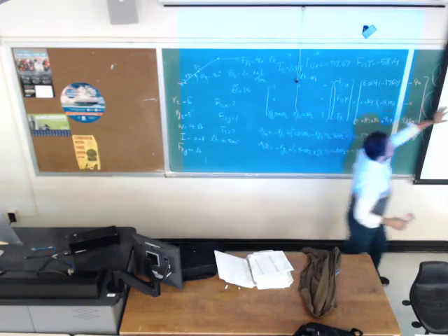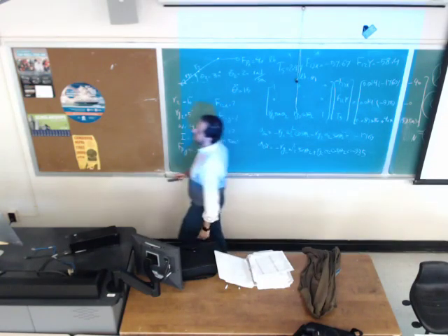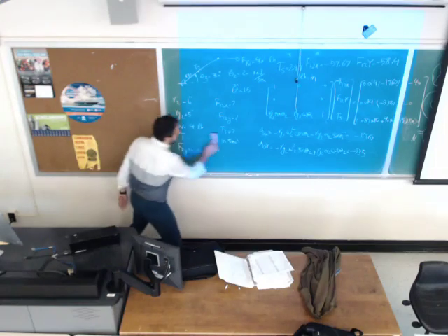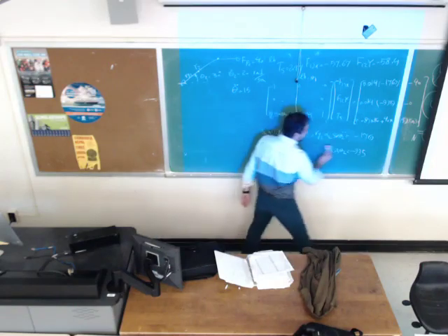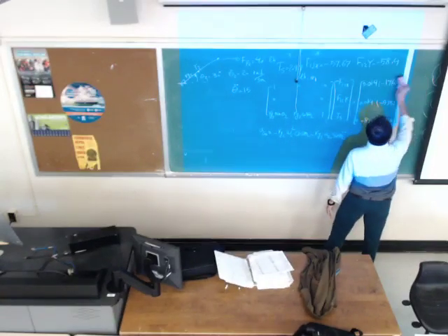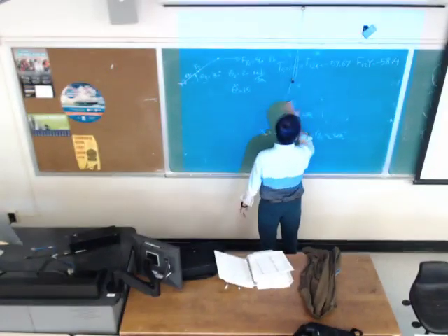So what we derived was a single link in pure rotation, but it's going to be the first link on the four-bar mechanism. We are going to do the same process for all 3 moving links, and then we are going to get 9 equations in the system of equations. It's going to be a very long process, but the process would be the same for all 3 moving links.